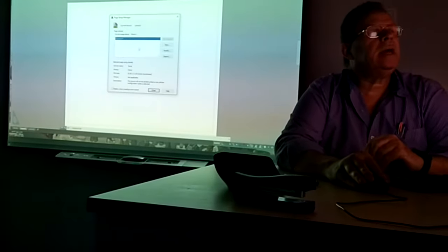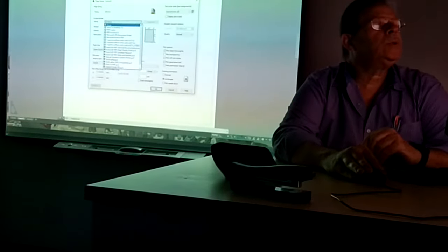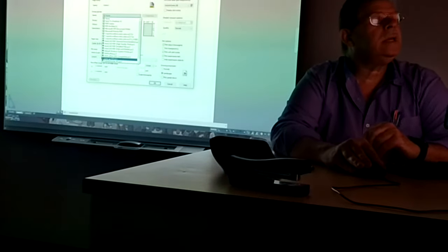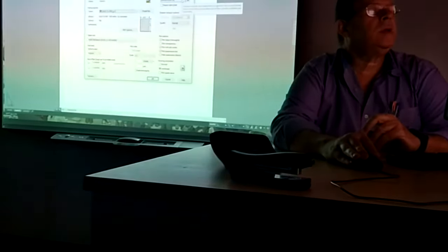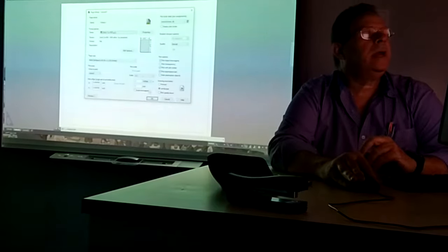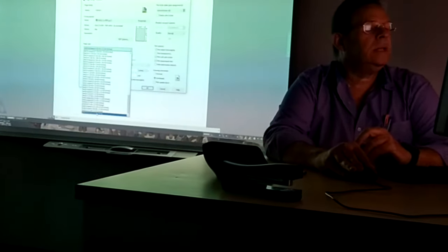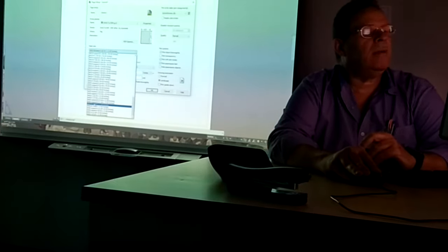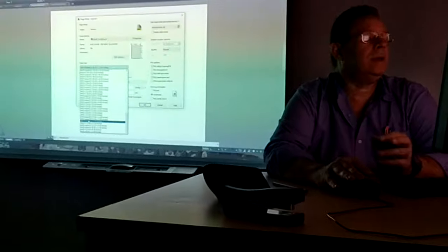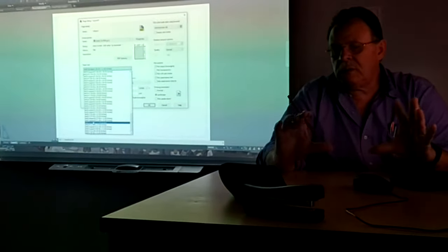In this case, I go to Modify, and then I look into a DWG. So we're converting DWG to PDF PC3 in here. Make sure you have this on monochrome. Then make sure you pick the paper that you want to print. In this case, NCB, paper B, 17 by 11. I like that instead of 11 by 17 because everything is in a horizontal format,